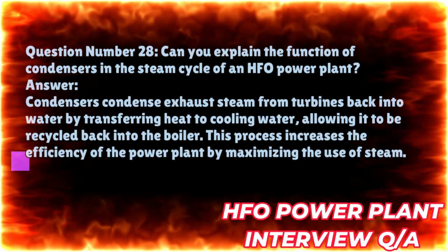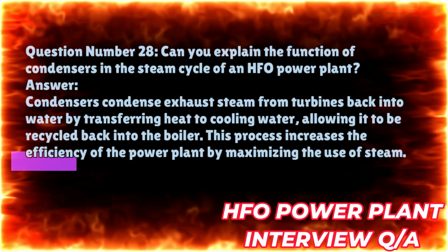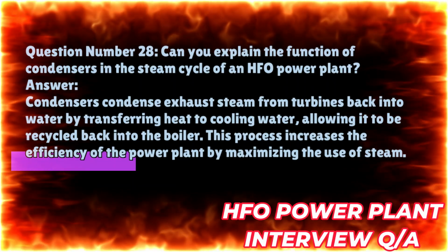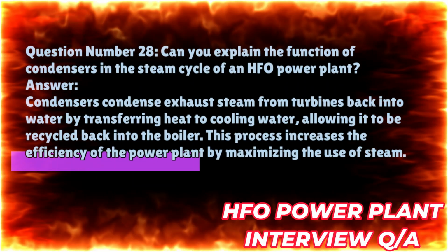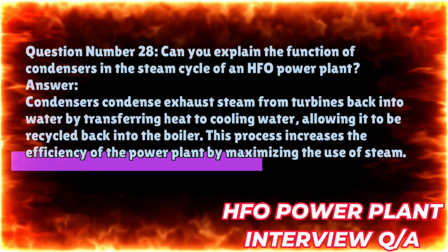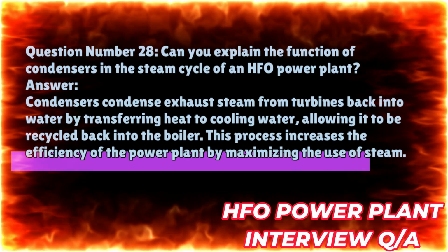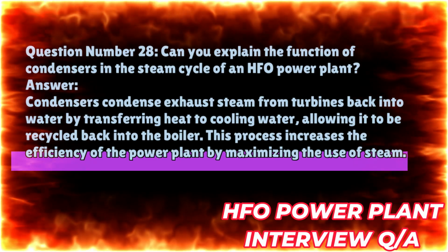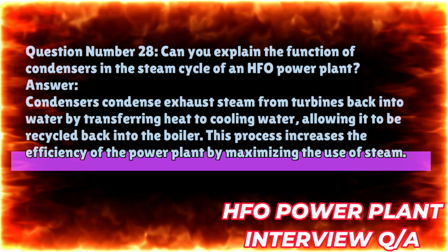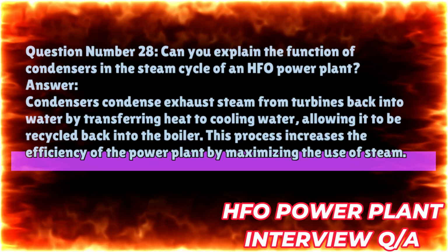Question number 28. Can you explain the function of condensers in the steam cycle of an HFO power plant? Answer. Condensers condense exhaust steam from turbines back into water by transferring heat to cooling water, allowing it to be recycled back into the boiler. This process increases the efficiency of the power plant by maximizing the use of steam.